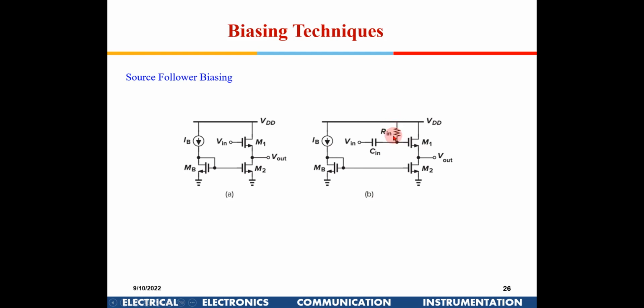Yeah, there is a high resistance which you need to put in here. But we are biasing this M1 at VDD. Yes. Sir, any reason for that? Normally VG is not that high. No, you can put in a slightly lower voltage than VDD also by using a resistance, but this also will suffice actually.